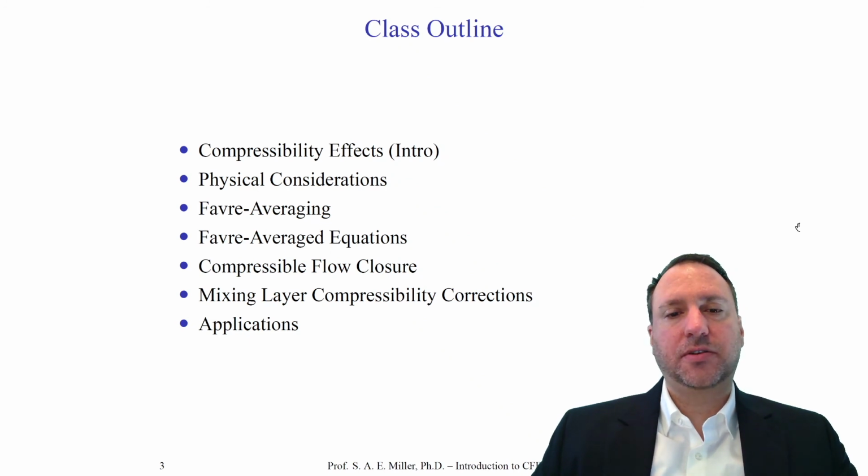We'll also look at certain physical considerations that are required when looking at a flow which has compressibility and turbulence. We'll finally look at a few turbulence closures that involve the compressibility effects, and then we'll look at some particular applications. You'll see that in contemporary CFD codes, often turning on and off compressibility effects for every type of turbulence model is nothing more than a click of a button. There may be no setting up whatsoever for some models because, of course, they're compressible themselves.